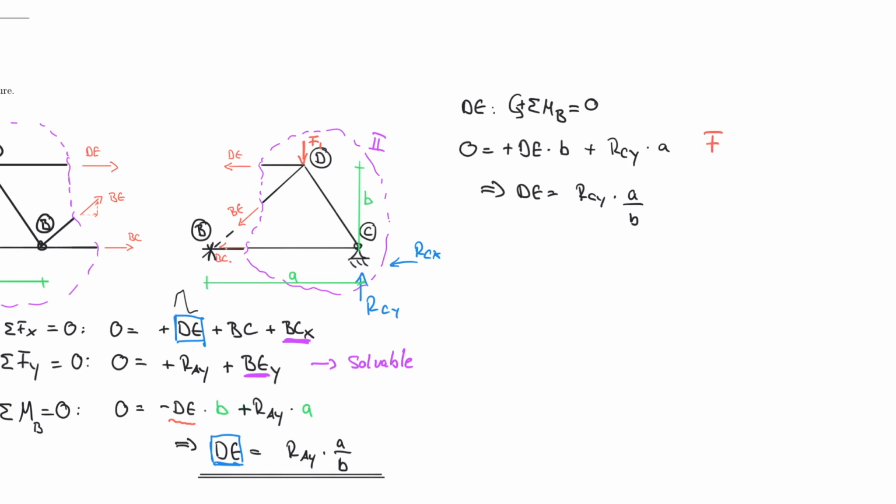So we would have F1, and that would now be technically multiplied by A over 2, right? Because we assume that node D is exactly halfway between node B and C. That's not very precisely drawn here, but that's usually how those structures are geometrically arranged. So F1 would be right at this point, turning about this point, so A halves. And in fact, it's turning clockwise, so therefore it's a negative part.